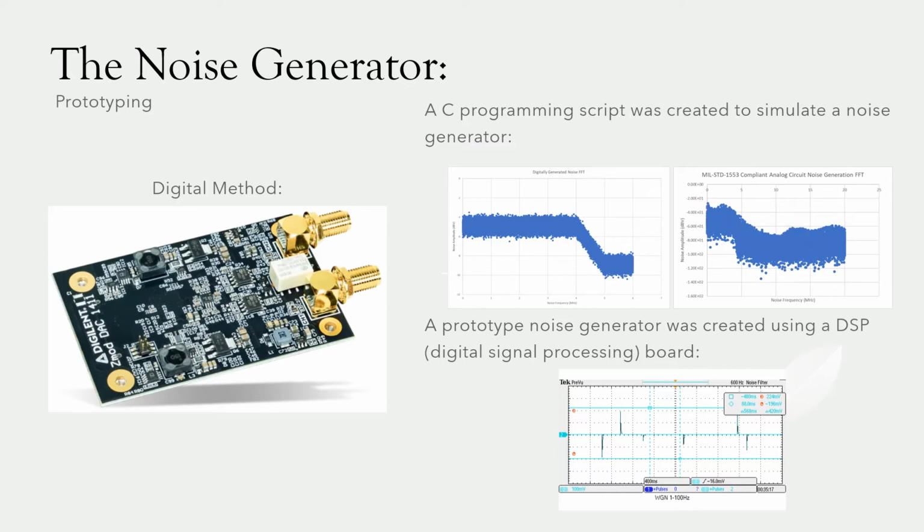On the right is the analog circuit equivalent that GE currently outsources to. You can see there are some deep valleys in the pass band, which isn't a very big deal, but there is also a lot of ripple in the pass band and a lot of ripple in the stop band. This causes higher amplitudes at higher frequencies, which can cause errors. And errors mean more data words need to be sent, and the test takes longer or will fail.